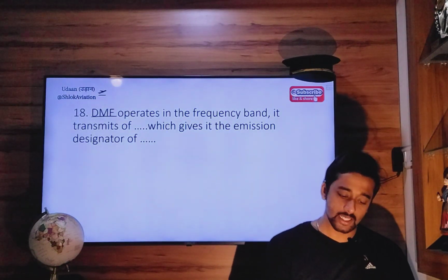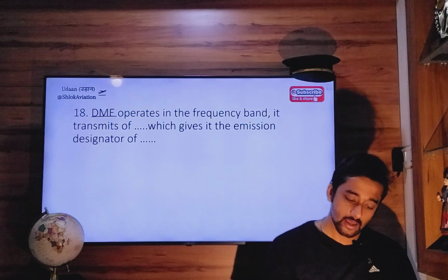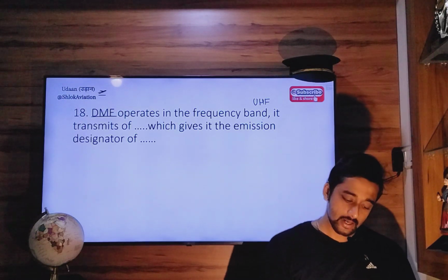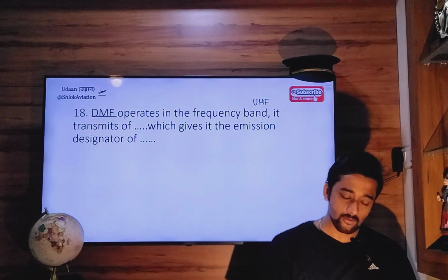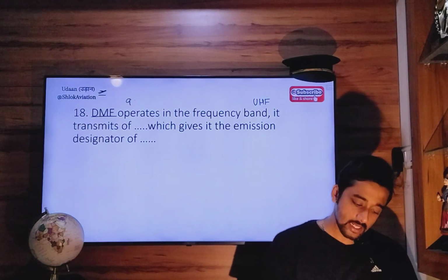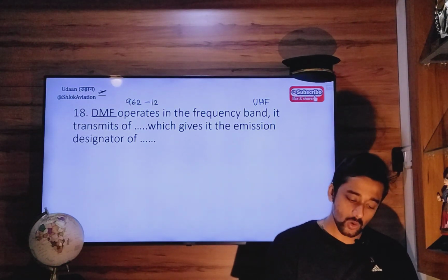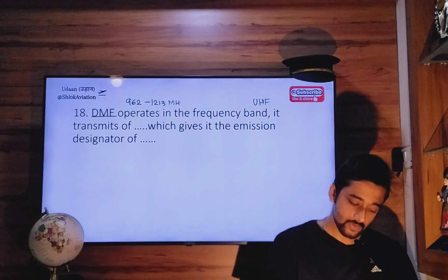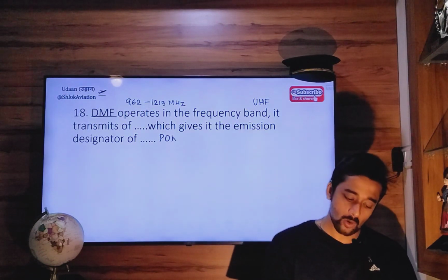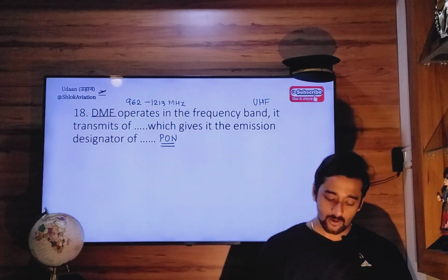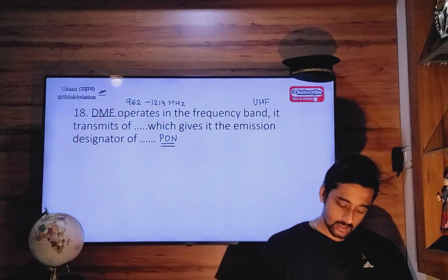DME operates in the frequency band UHF. It transmits in the frequency band, what frequency band is it? 962 megahertz to 1213 megahertz. And the designator is P Papa 0 November. Now, what is the meaning of this Papa 0 November? That is very important.